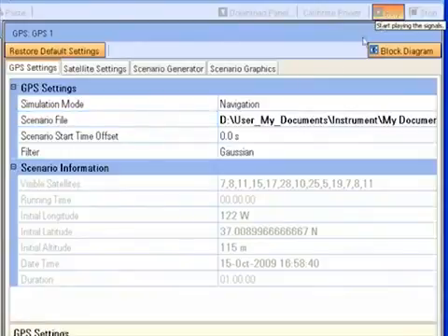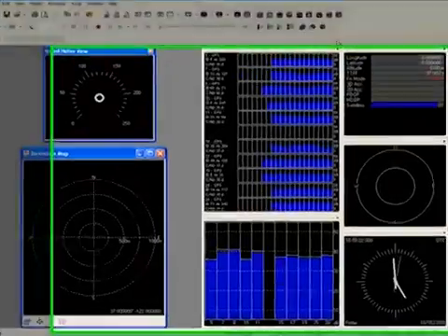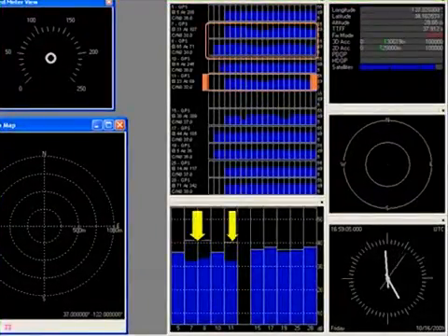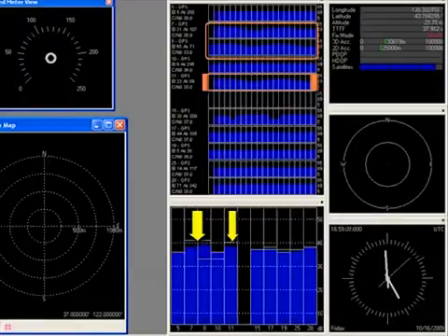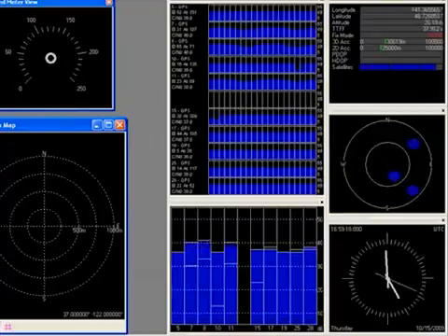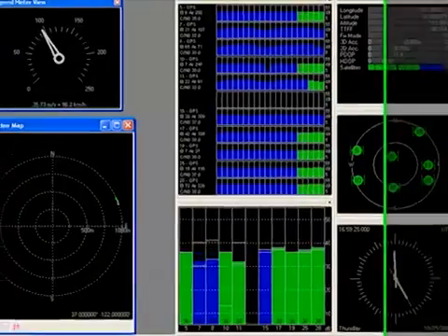On the GPS receiver software, we see the same 10 satellites as we did in the previous demo, but now we can see that the satellites with multipath, numbers 7, 8, and 11, are varying in power. This can be clearly seen in the satellite level versus time display. The power levels fluctuate above or below the power of the other satellites as the line of sight and the multipath signals either add or subtract from each other depending on the phase of the signals.